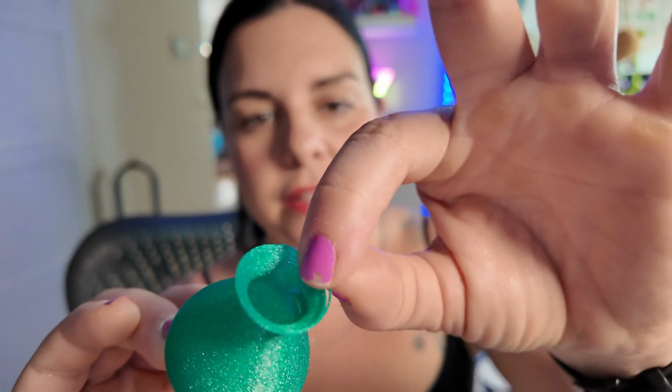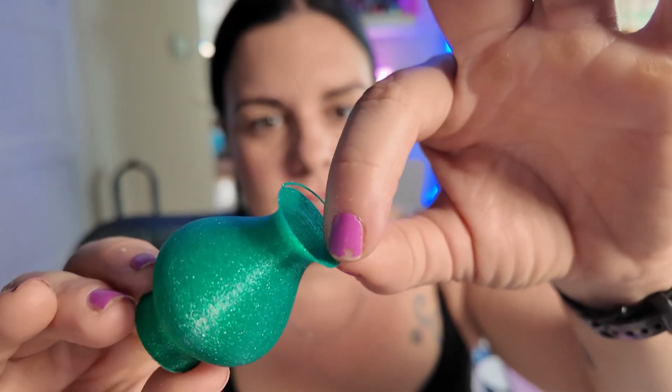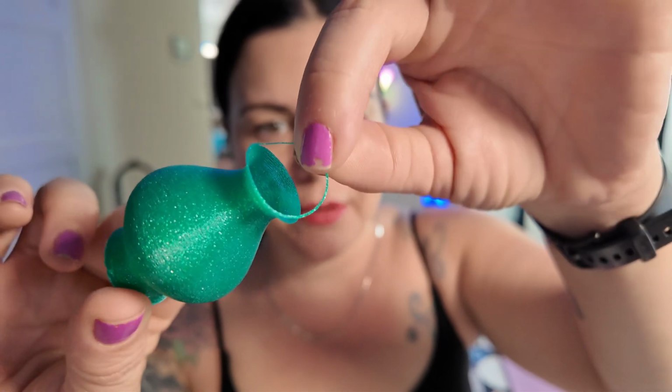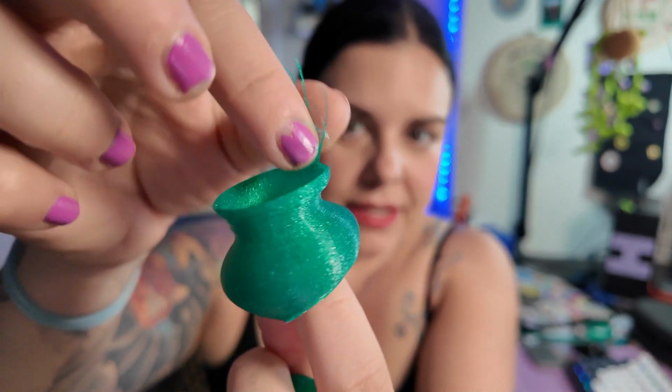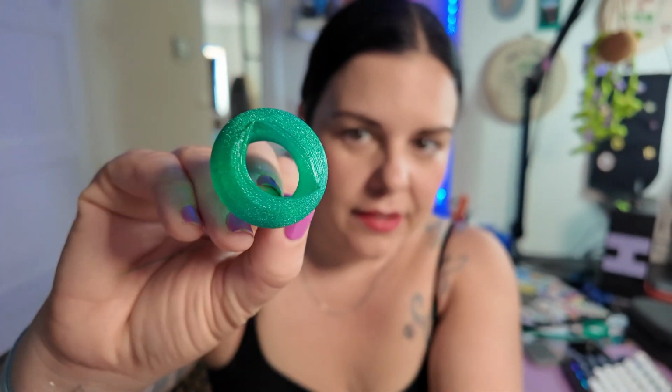So the thing with vase mode is that you have to watch out for the design, because it can be harder to print some parts, some angles, since it's just so thin. You can see here the layers kind of coming out. It can be a fragile print also. I tried this one that failed. Here you can see the bottom.